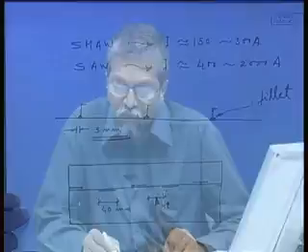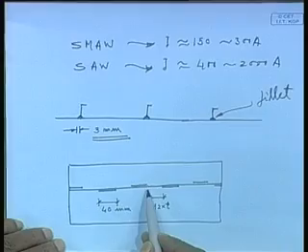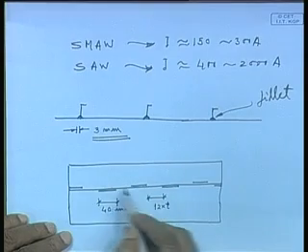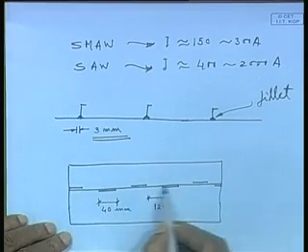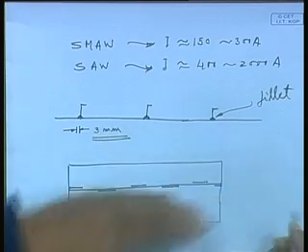The structures become more prone to corrosion in such kind of welding, for the obvious reason, the unwelded parts remain exposed to moisture and corrosive environment. Because what is happening, you imagine this central line is the line of the web, a stiffener has been welded, right.